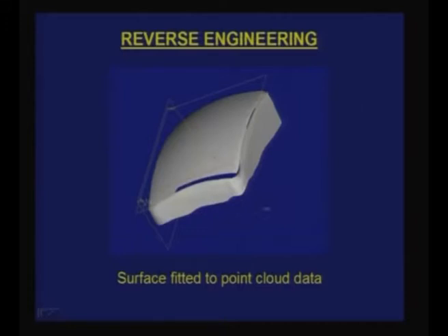So once you do reverse engineering, that is, build a surface, you need to do some stitching and blending operations in order to fill the gaps, which can be done either in high-end CAD/CAM systems with a lot of effort, or using specialized reverse engineering software where this can be easily done.